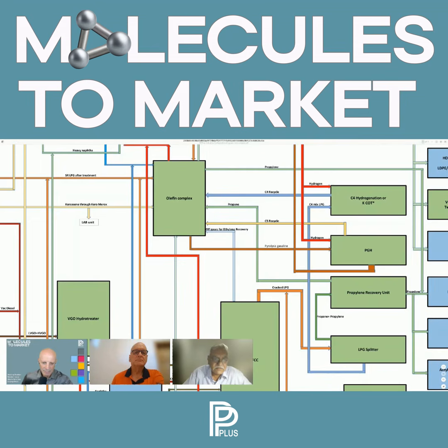But the question comes of the olefin plant. Now, olefin plant puts you in some trouble. For the olefin complex, there are only 4 licensors in the world. UOP doesn't have a technology, incidentally. So it's either Technip, which was originally Stone Webster. Technip also has their own technology, but Stone Webster is a premier technology there. Then you've got ABB Lummus, who are premier in the liquid crackers. You've got Linde, and you have KBR, millisecond cracker. These 4 are the prominent olefin licensors.